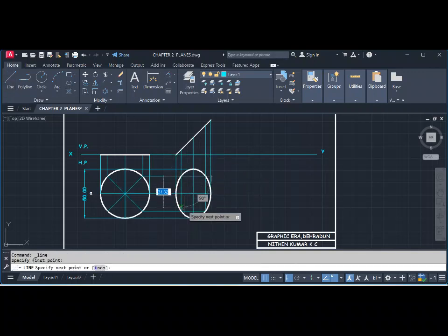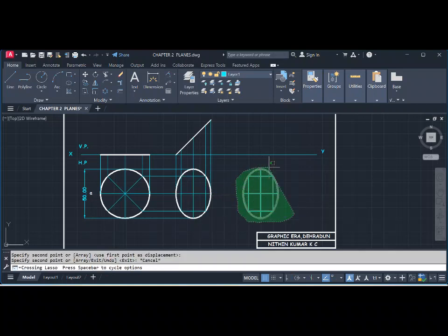So to make this next step easier, we need to trace the lines inside the ellipse nicely like this, this line from here to here and like this. So when I select this particular ellipse, then automatically I am going to select the lines inside the ellipse. So now easily I can get the next step. Now select this here, keep it somewhere here, then you need to rotate it here like this, and the resting point, this is where exactly generally A will come. So as per this first position here, it is inclined to VP at 50 degrees. It is done, 50 degrees.